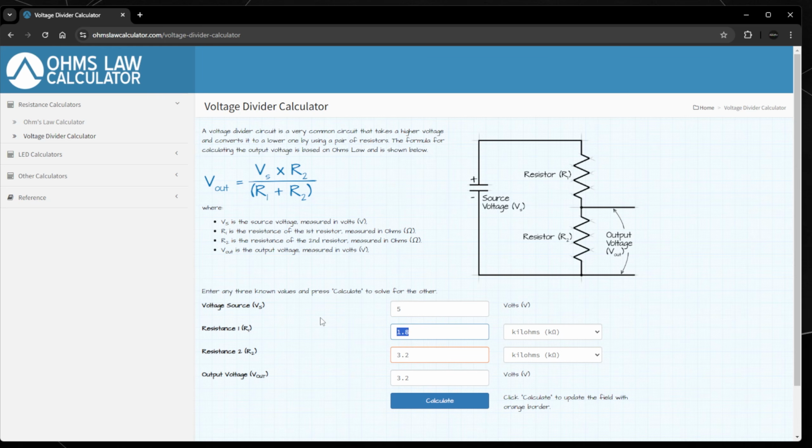So they're good numbers. Now, you can use different ones. You could update this to 5 kilo ohms if you want, and then you'd have to have 8.889 or, 1 kilo ohm here, maybe 1.7. As you lower and increase these numbers, you lower and increase the amount of current going through. And we want the combination of these two to be pretty much 5,000. And I'll admit, I'd figured this out already. So I knew that 1.8 thousand plus 3.2 thousand is exactly 5,000.